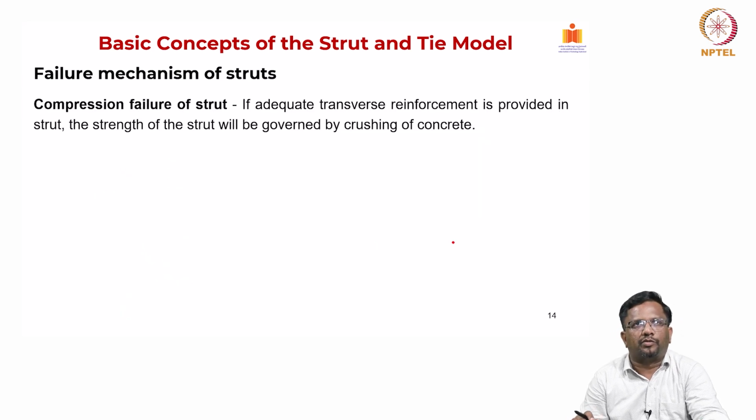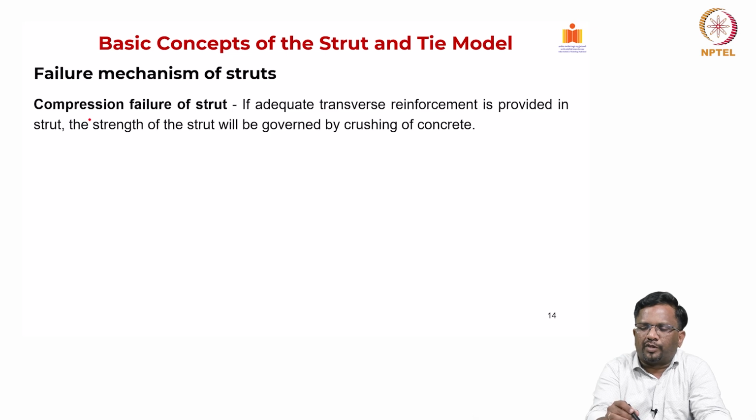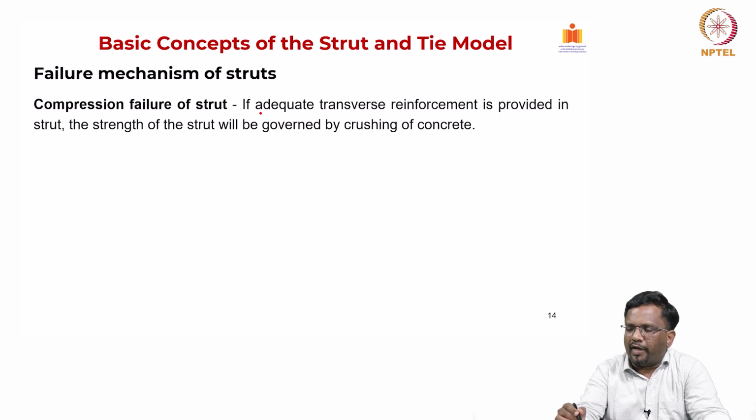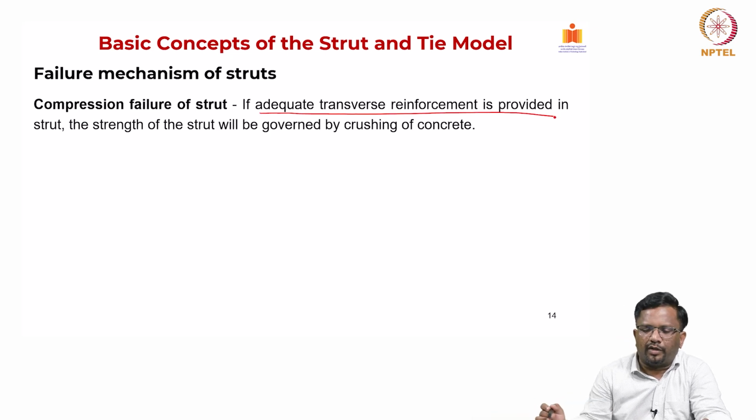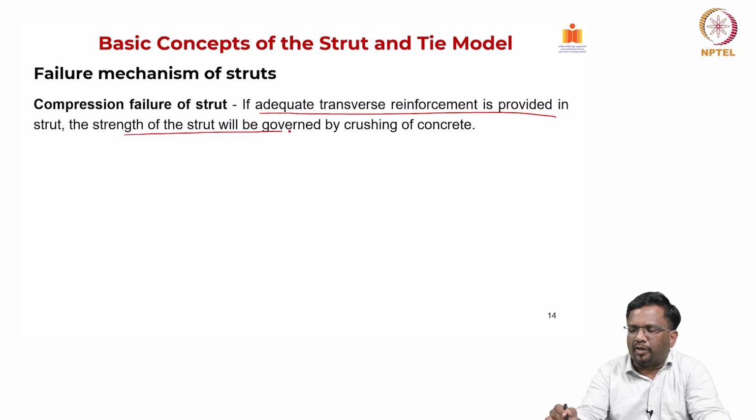Now, regarding the failure mechanism of the strut: if adequate transverse reinforcement is provided in the strut, then the strength of the strut will be governed by crushing of the concrete, that is, compression failure of the strut.